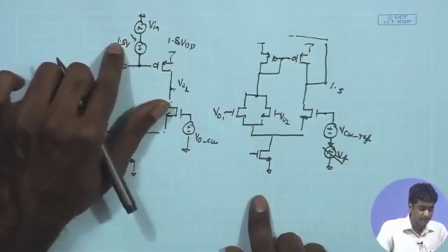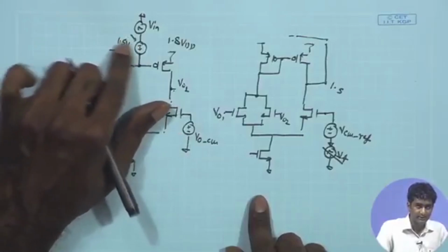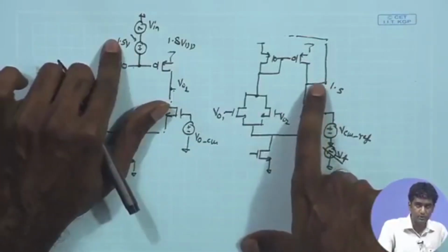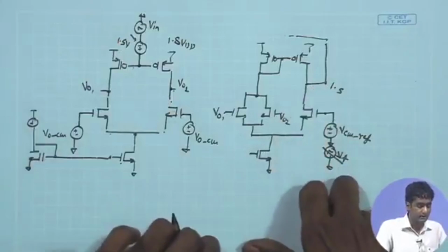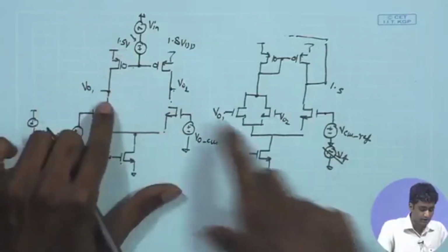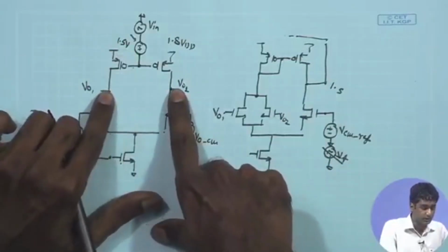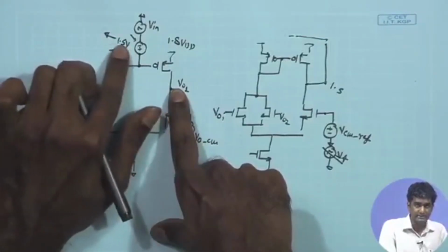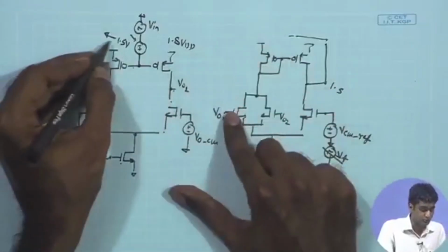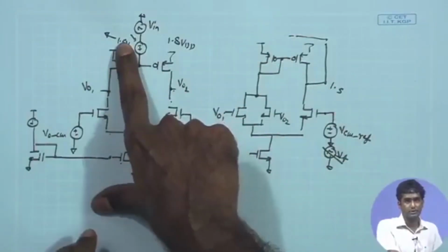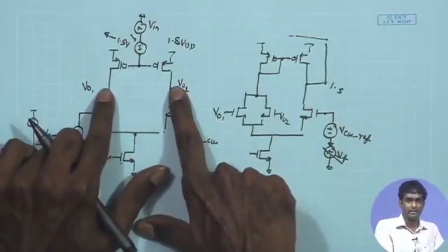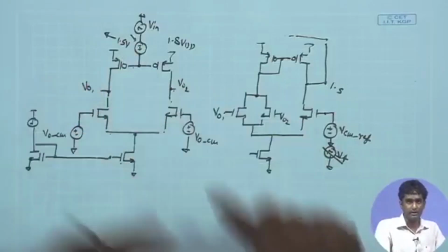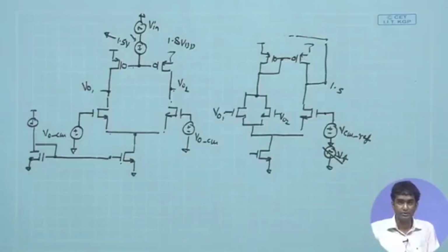Also, if you look at the DC value, you have to put very precise values over here, which was the same as the value provided by the feedback circuit, and if you are not getting the exact same DC potential over here, it is also advisable to sweep this 1.5 volt DC across the mean value. So, you are expecting that the 1.5 volt DC put over here will give me the right DC potential over here, which was under the closed loop condition.